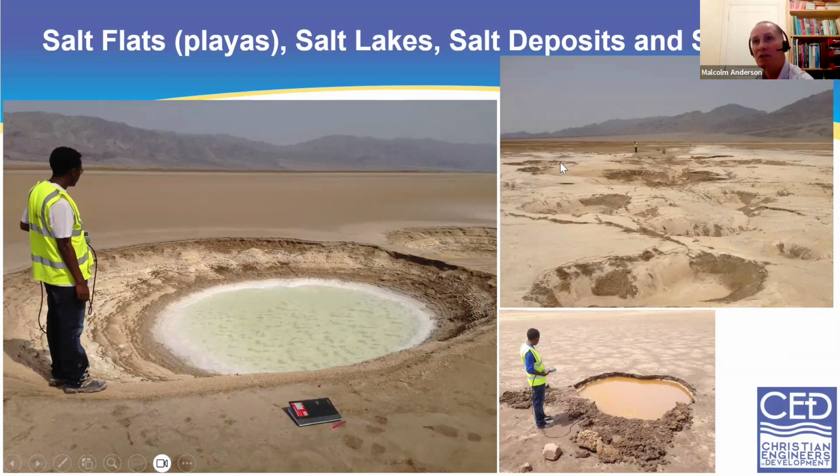Incidentally, there are other shots here. Here's a whole load more sinkholes. These are associated with faults that are inside the salt, and when you track these sinkholes, you can track where the fault is below, and the fault is what is releasing the fresher water into the salt zones behind underneath it, and that's causing the dissolution that's causing these sinkholes.